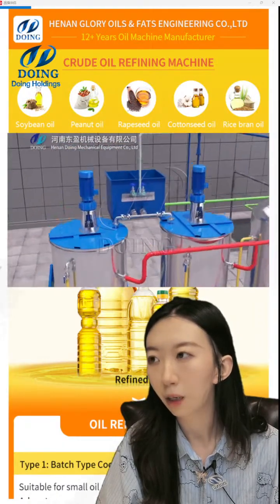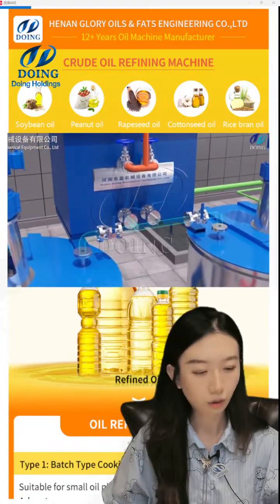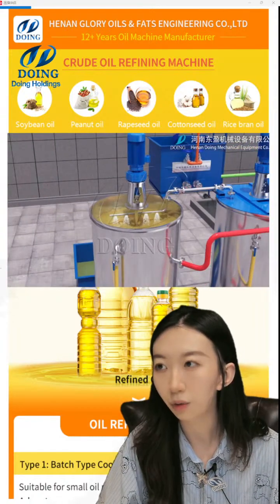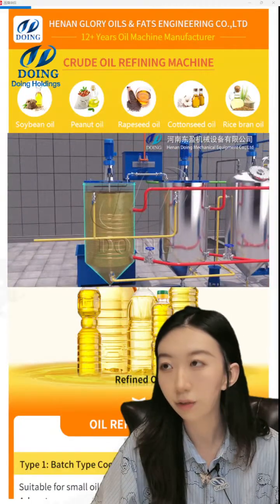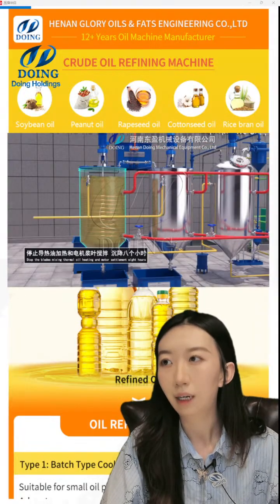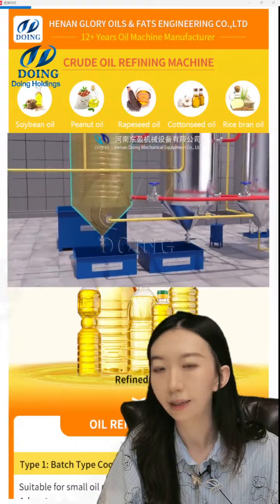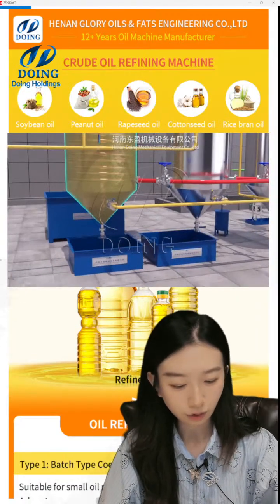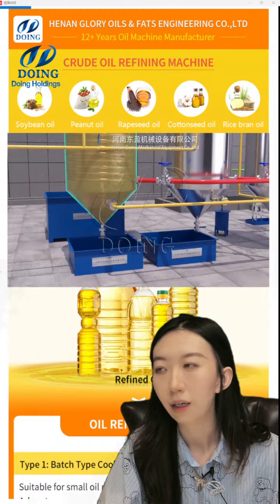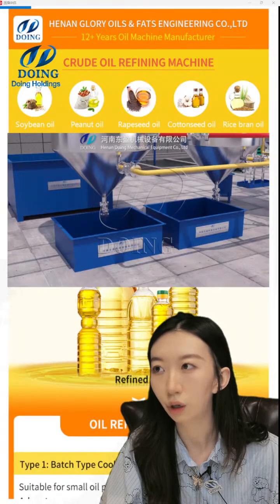During degumming, we should use phosphoric acid to increase the hydrophilicity of the colloidal impurities. After the phosphoric acid, we add some hot water to the crude oil.